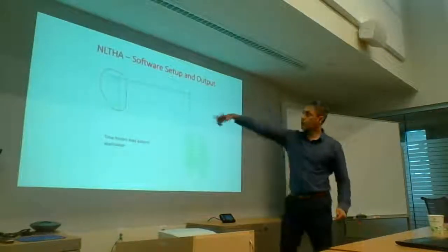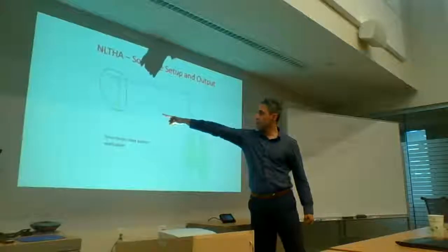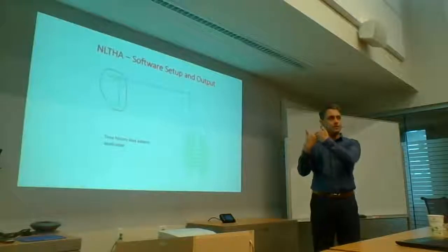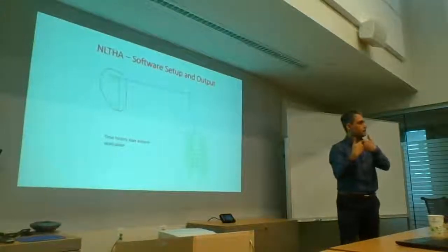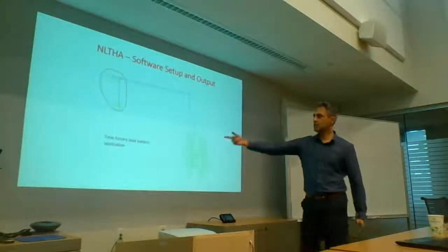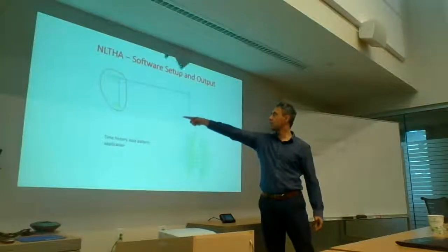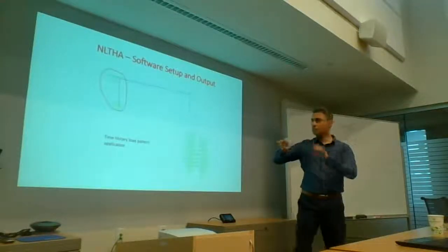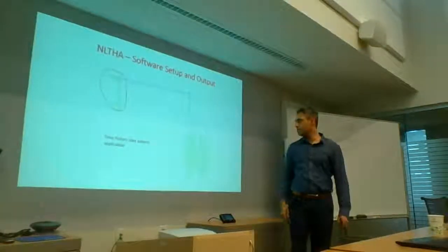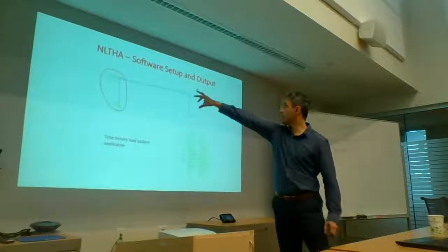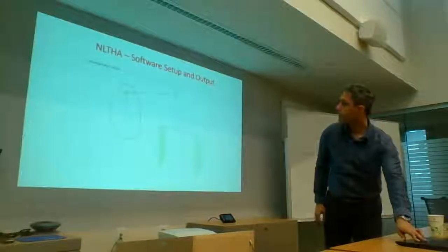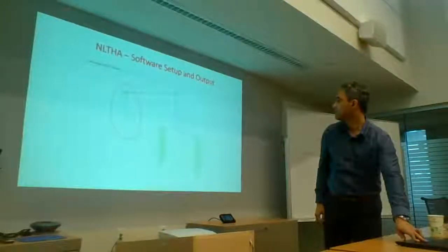So this thing is a wall. It's got some soil behind it, some soil underneath. So this is just like I was talking about the mode shape for the pushover. This is just going to tell the program, look, this is a time history load pattern. You apply a unit there, a unit there. It doesn't mean anything. It's just telling it, this is where you're going to go and apply your time history record in this direction. Okay, so we introduced it there, and then we were trying to study this whole thing. One was longitudinal, I believe. One was transverse.